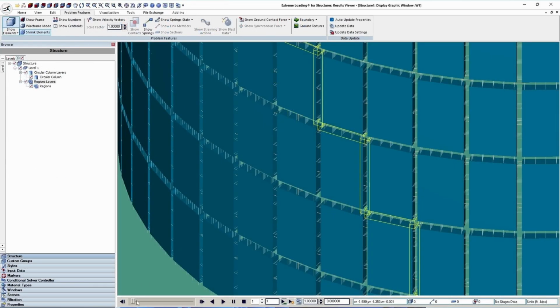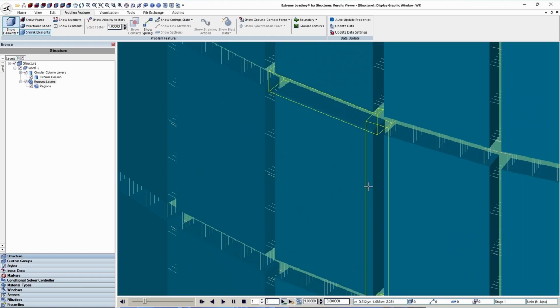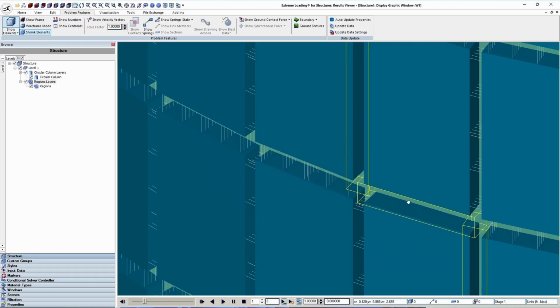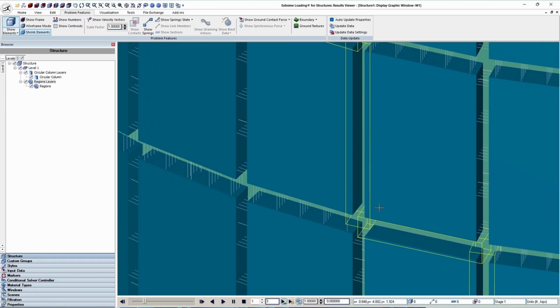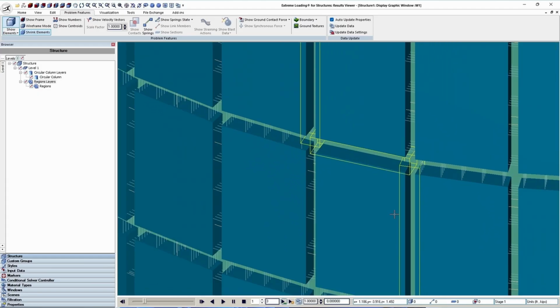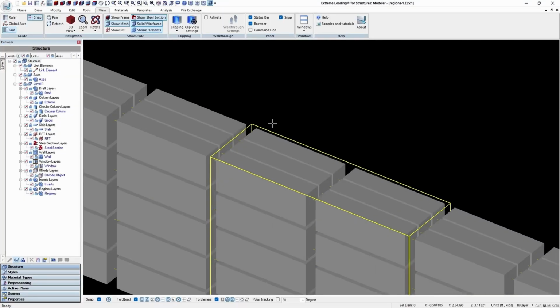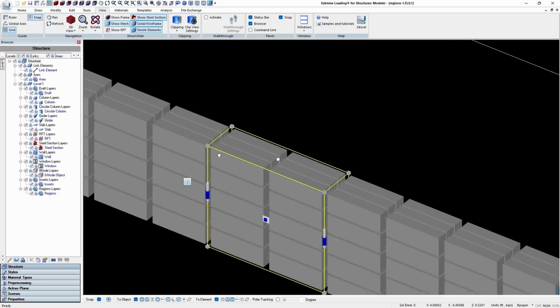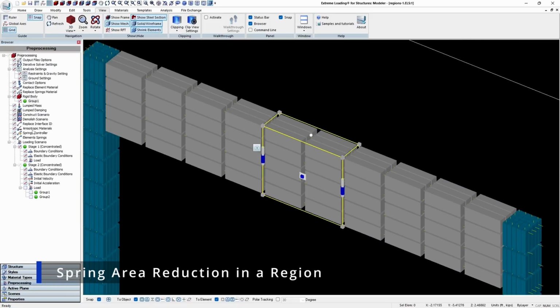In the shown problem, the springs inside the bounds of the created regions were removed, and thus a crack was introduced. The regions feature lends itself well to the spring controller pre-processing action, so we'll use one such case to show the process of applying a pre-processing action to an 8-node region, since it is the same for all pre-processing actions.